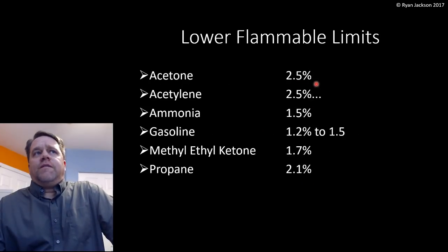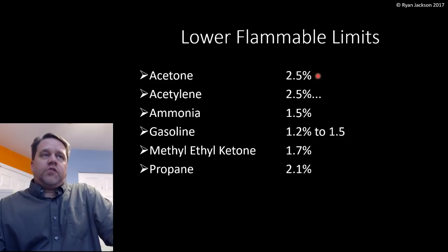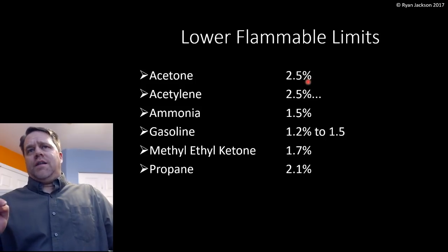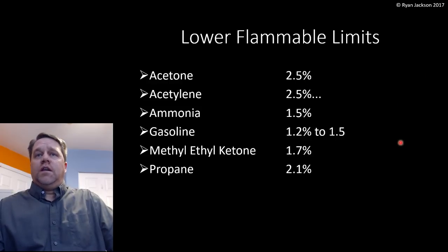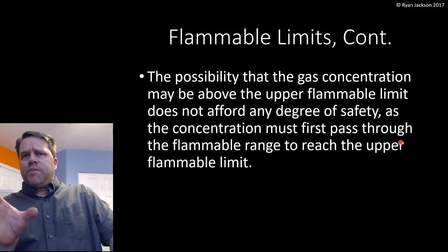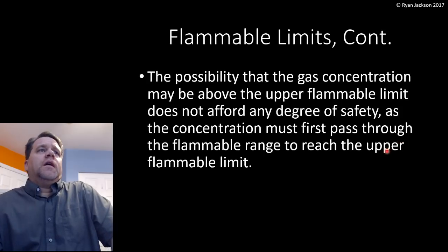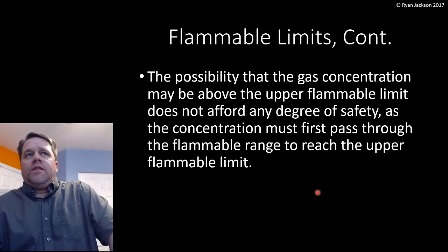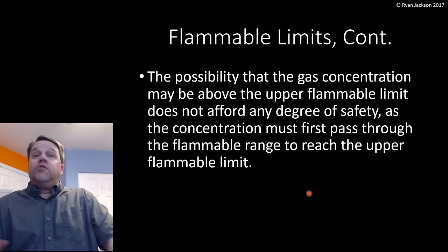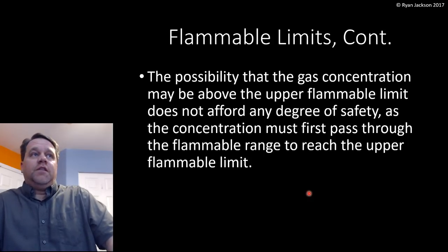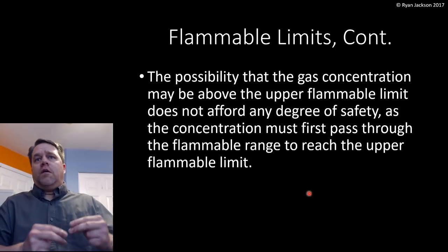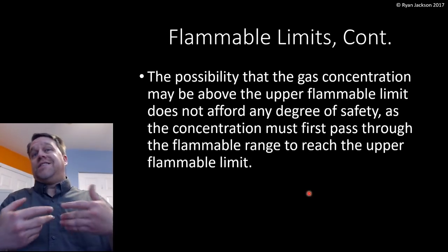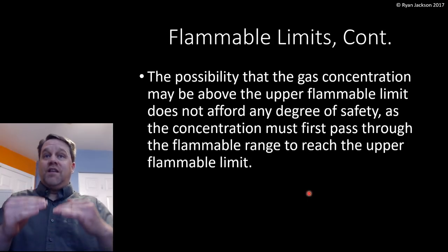Acetone, 2.5%. If I have 2.5% acetone and 97.5% air, that will ignite. I skipped a slide here and I did that for a reason. The possibility that the gas concentration might be too rich or above the upper flammable limit really doesn't provide any safety, because in order to become too rich to burn, at some point you were in that zone that it was flammable.